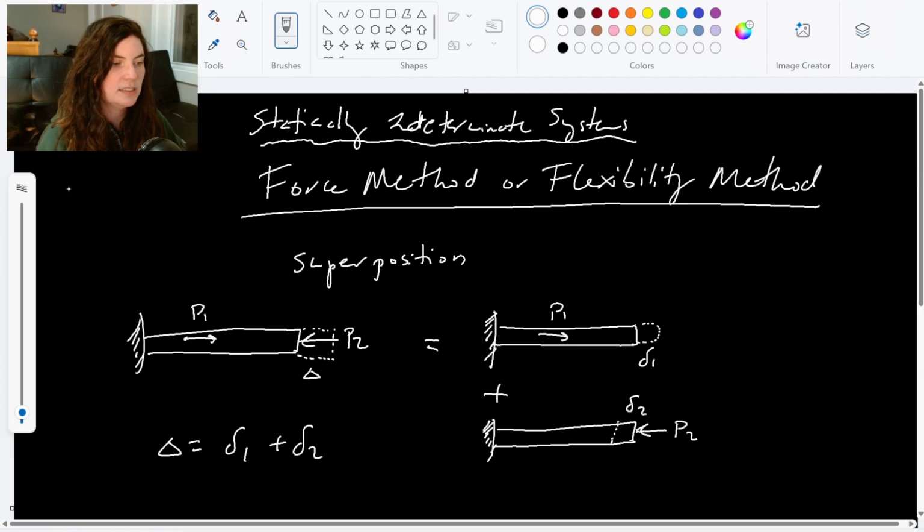All it says is that for each load component separately, we can sum the stresses or the displacements of those individually. So we can sum these individual displacements caused by each individual load, and that gives us the same as the overall displacement. So it's a really handy tool we can use, right? We used something similar when we were talking about axial load. So this idea of superposition is how we're going to tackle this.